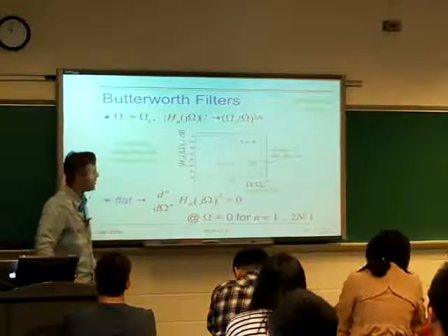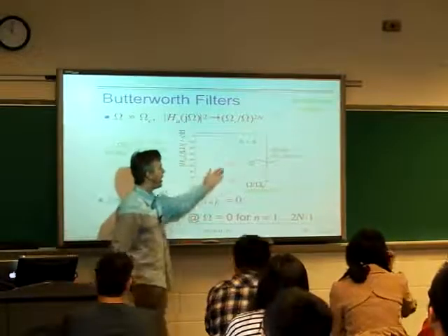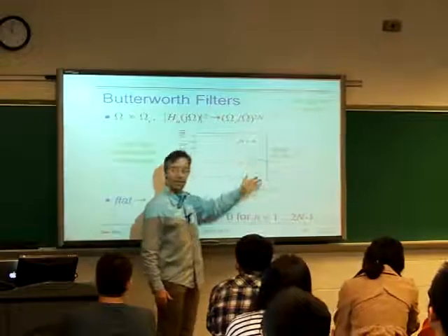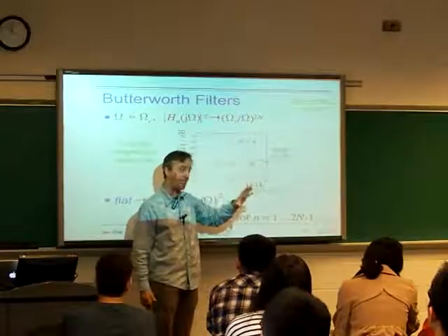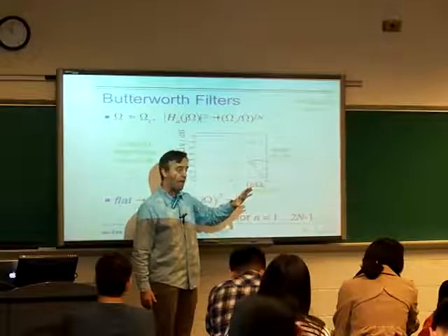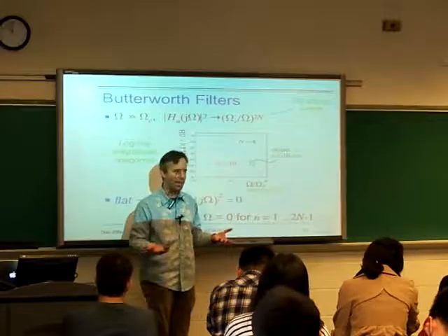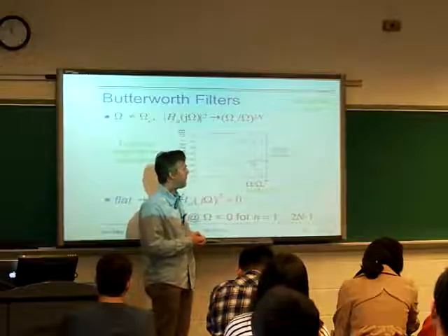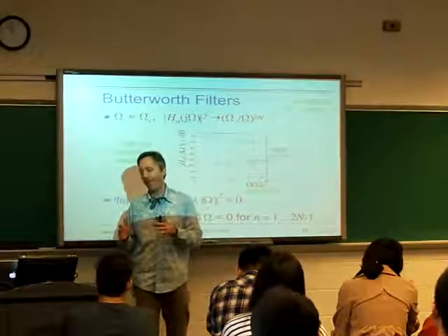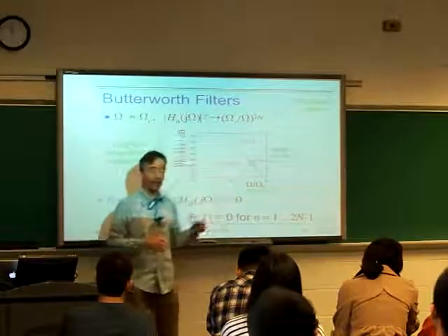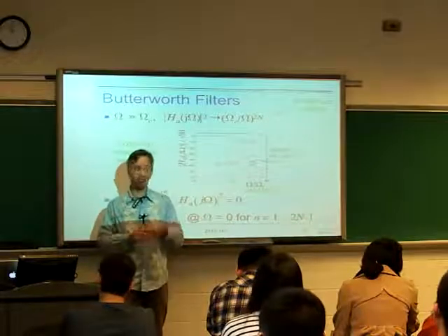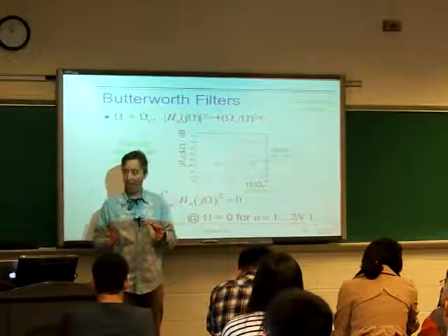Yeah, that's interesting. So the idea here is that what I've said is the slope depends on all the poles, right? The order n is the number of poles that we have. And so the question is, well, that sort of means they all have to be in play at the same time. Well, we haven't said where the poles are. And of course, the point about this Butterworth filter is that the poles are all carefully arranged to give us the exact behavior we want.